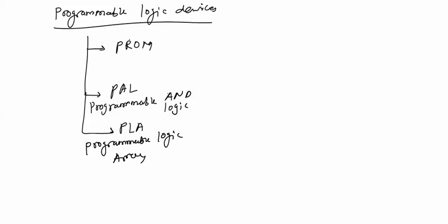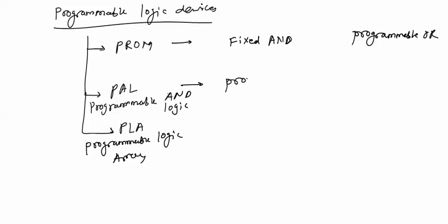Now for PROM, it has a fixed AND operation that is not programmable, while the OR is programmable. In PAL, there is programmable AND and fixed OR.